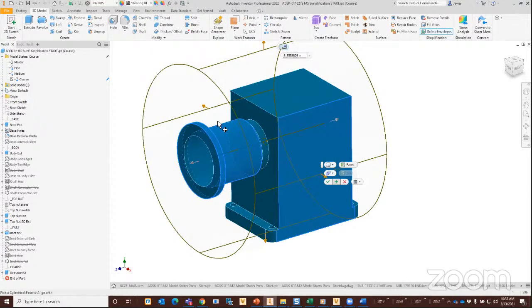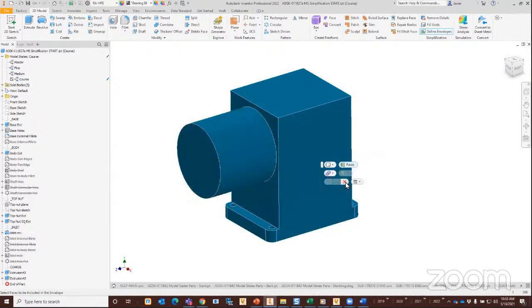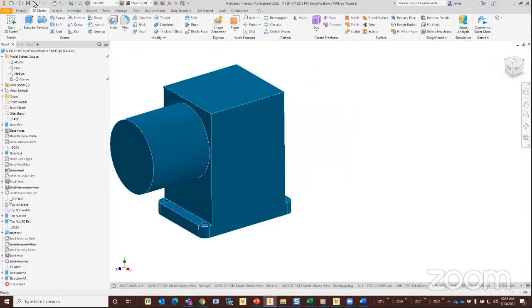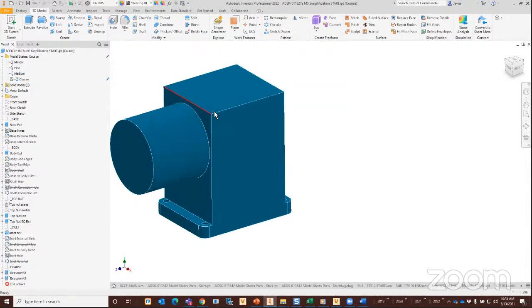And you can see I've got buttons here that'll help me snap to maybe this larger diameter. Arrows here that'll let me snap and size maybe up to this face. And let's make sure I'm getting up to the very end of this here. So all of that is going to sort of encompass what you see here and give us a really coarse representation of this. Okay, so here's my really coarse representation of this, and I'm going to go ahead and save it. So I now have a fine, right, a medium, and a coarse.